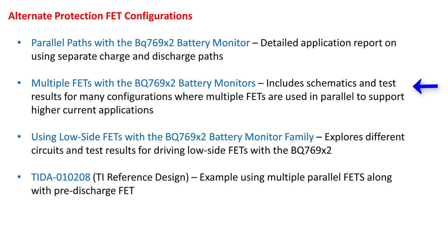It also includes valuable discussions on reverse charger protection circuits, guidance for the optimal charge pump capacitor selection, and a more detailed look into the charge and discharge driver current paths. For applications where low-side FETs are required, the low-side FET application report covers multiple different options, like using a FET driver IC or using discrete components. The TIDA-010208 reference design is a good example where multiple parallel FETs are used along with the pre-discharge FET.